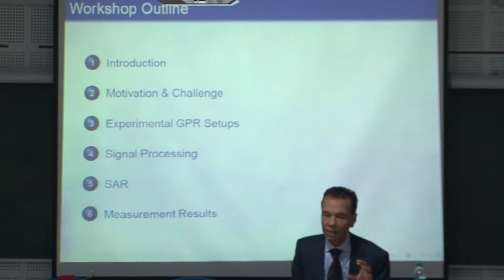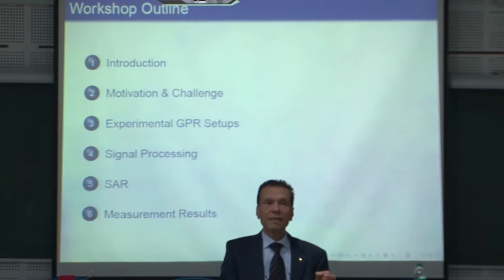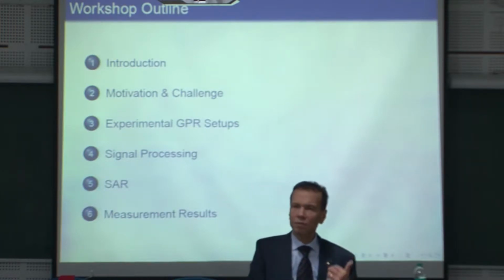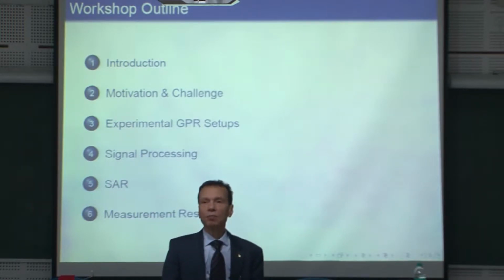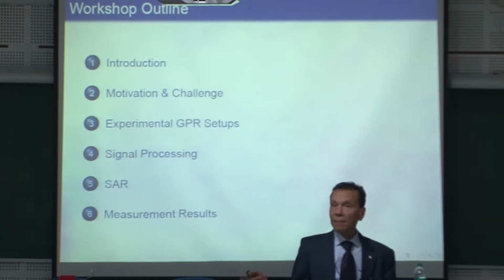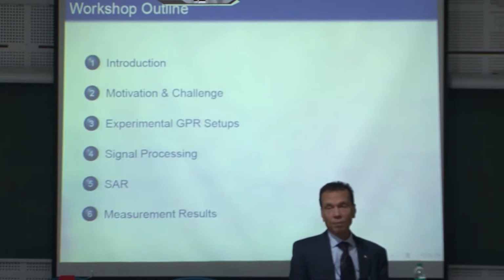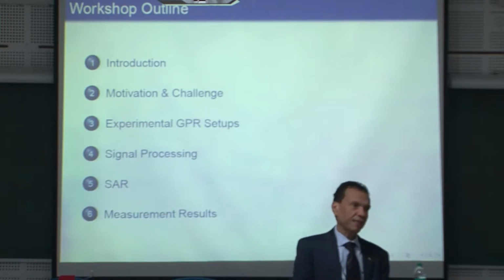Okay, what are the technological problems related to that? It is actually the stability, because you should, as an engineer, think, I'm standing here and I decide to capture the signal when I'm receiving or to send the signal. Okay, now I save this, I register this in a record, and I go to the next position and I do the same. I must synchronize, so I have a synchronization problem. Any deviation from the synchronization will cause artifacts.